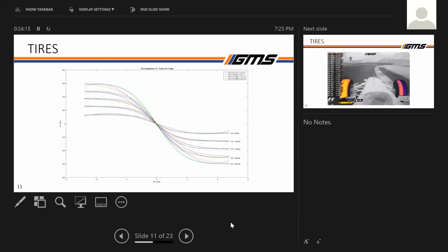We'll bring the car in and give it a visual inspection, make sure nothing's broken, and then look at the data and see if anything looks off with the dampers. That could indicate there's a problem somewhere on one of the corners. We look over the data and make sure nothing bad is happening, no weird anomalies in the data.